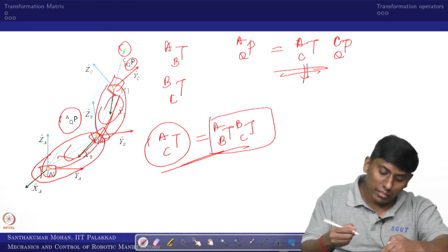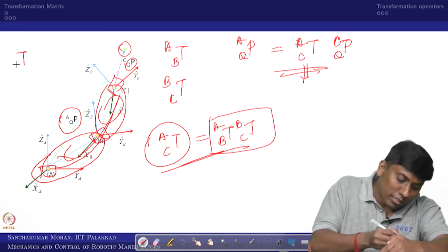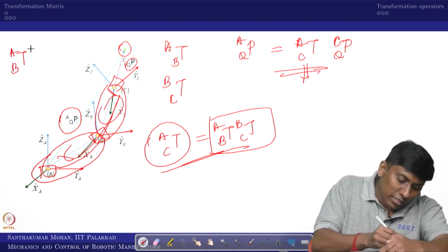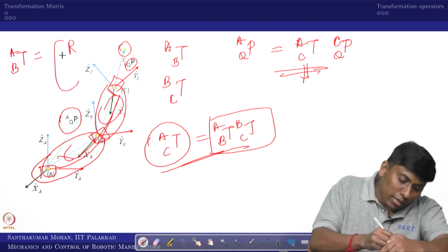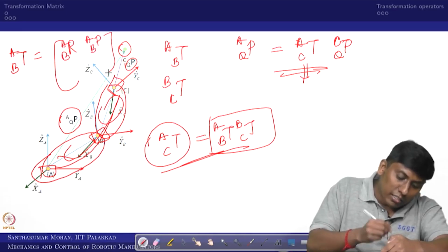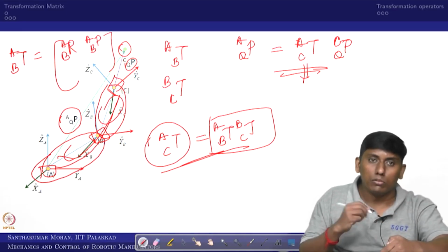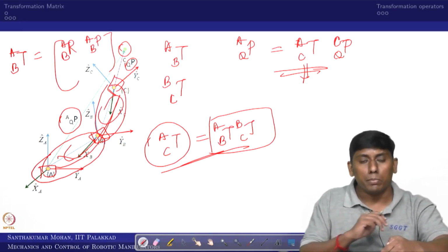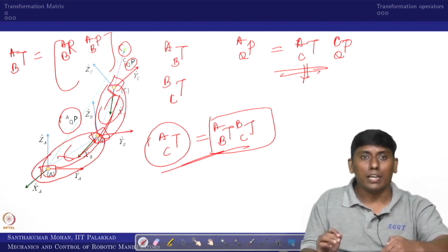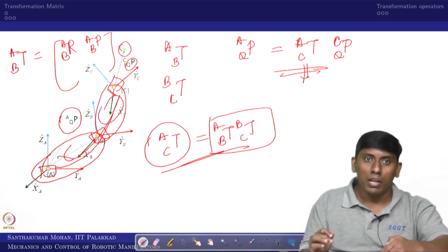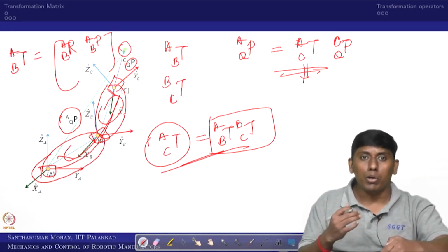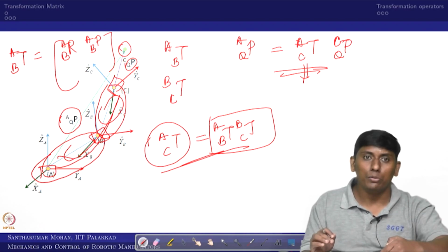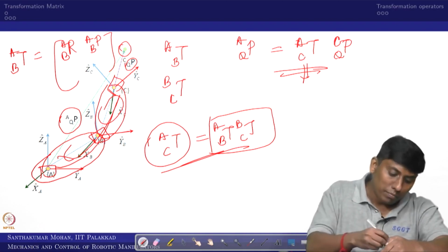But this can be written in this form, right. So, the general transformation matrix would be a rotation matrix and a position vector, and conventionally we assume that there is no perspective, in the sense the perspective vector we consider as 0, so it is always an orthogonal view. And for lectures, we always assume that everything is in a single unit, in the sense the scaling factor is 1, okay.